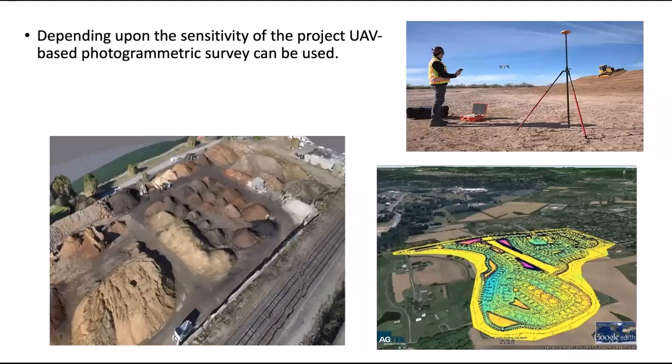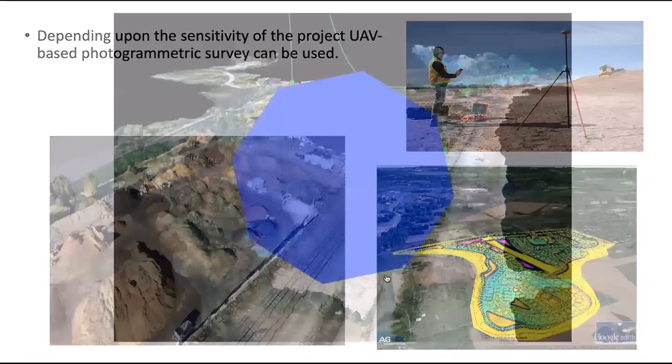You cannot use this type of photogrammetric technique yet. They are not as accurate yet. But for earthwork, which is one of the most advanced areas in recent decades, you can save a lot of time. You can also measure the quantities just by clicking around it here. So you should know the sensitivity.